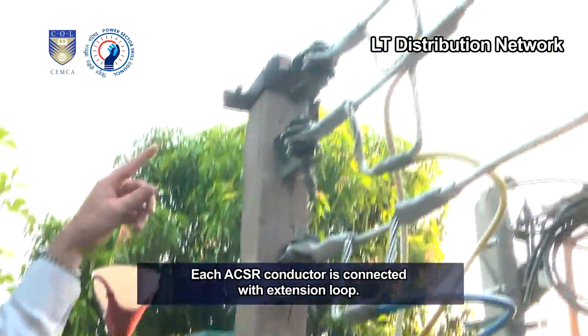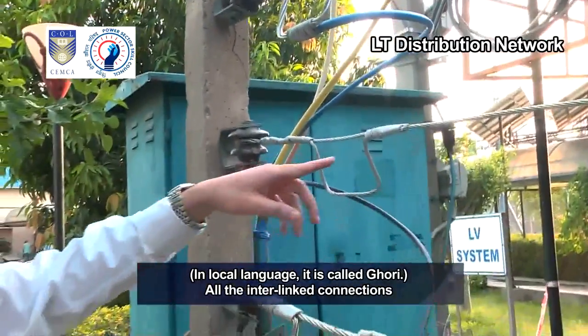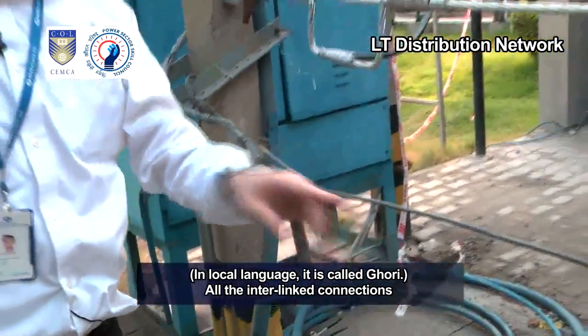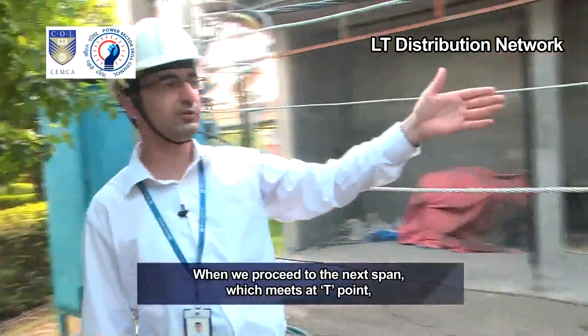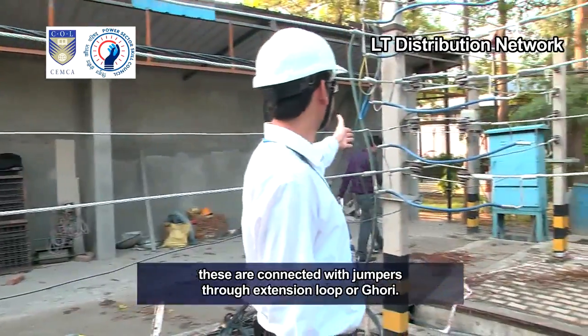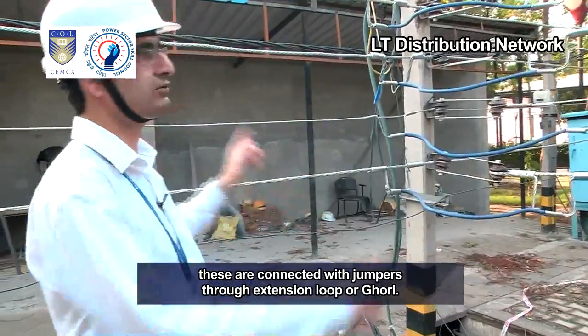Each ACSR conductor is connected with extension loop. In local language, it is called ghodi. All the interlinked connections to the lines are made from these extension loops. When we proceed to the next span, which meets at T point, these are connected with jumpers through extension loop or ghodi.